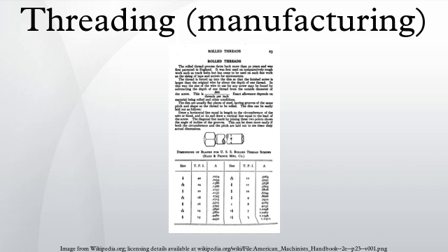Conical micrometer anvils, specifically suited to resting on the sides of the thread, are made for various thread angles, with 60 degree being the most common. Micrometers with such anvils are usually called thread mikes, or pitch mikes. Users who lack thread mikes rely instead on the 3-wire method, which involves placing 3 short pieces of wire of known diameter into the valleys of the thread and then measuring from wire to wire with standard anvils. A conversion factor is then multiplied with the measured value to infer a measurement of the thread's pitch diameter. Tables of these conversion factors were established many decades ago for all standard thread sizes, so today a user need only take the measurement and then perform the table lookup.